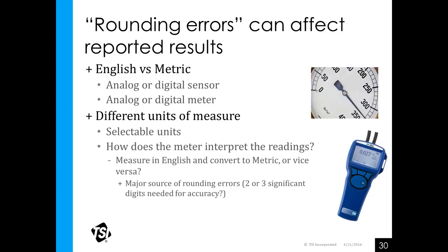Currently now, for pharmacies, USP 797 requires differential pressure measurement in compounding pharmacies. So a reading of 0.016 inches of water column might be displayed as 0.02 water column. Which one do you report? You've got to look at the requirements for that application. Do they need 3 significant digits, or can they settle with 2? Again, it all depends on what's required for that application.